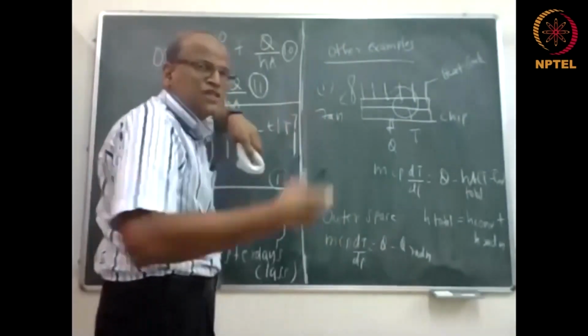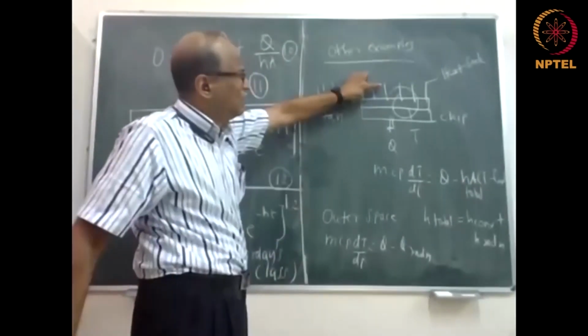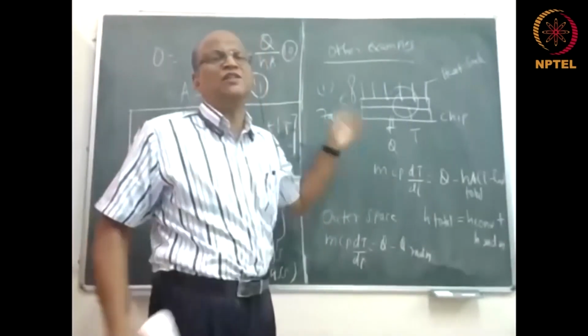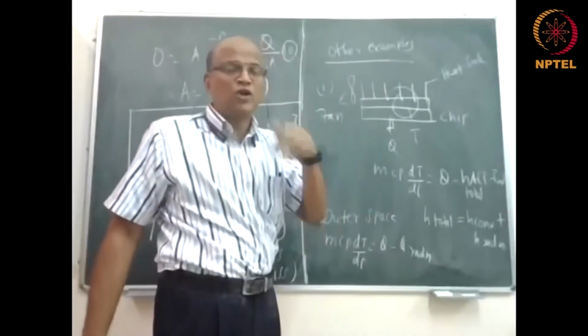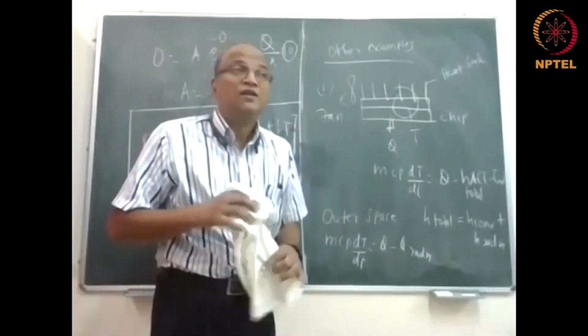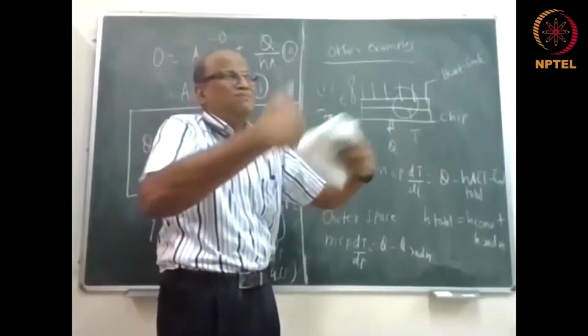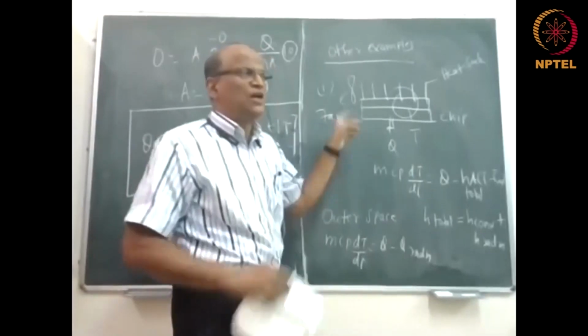And the motivation for the inverse problem is that you might have assumed some emissivity. But if you start getting measurements, as an analyst you want to find out whether the emissivity is okay or not. What you expected is different from that. Then how does it enter? How does it get fed back into the system? In your next launch vehicle, in your next mission, you will correct the emissivity.